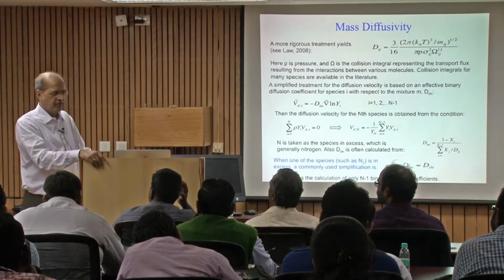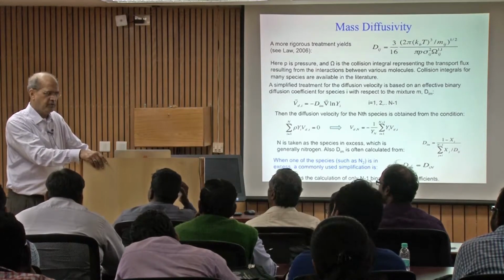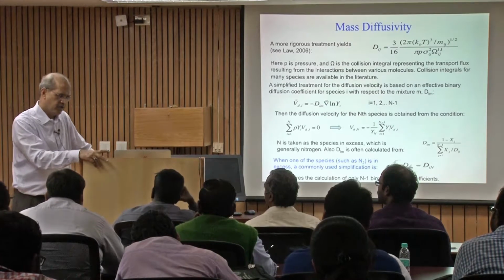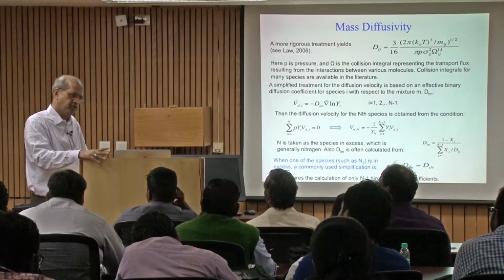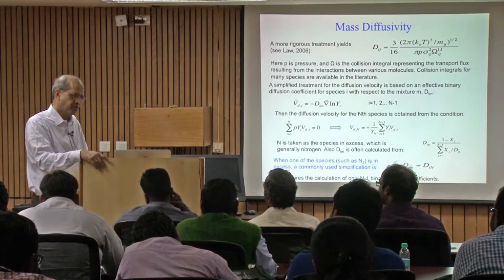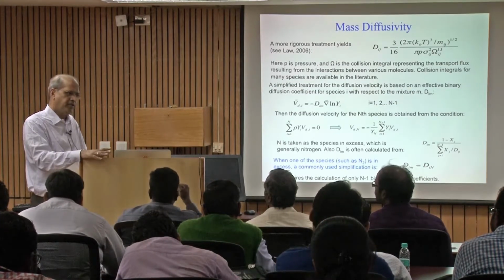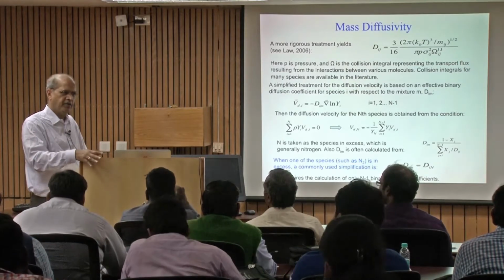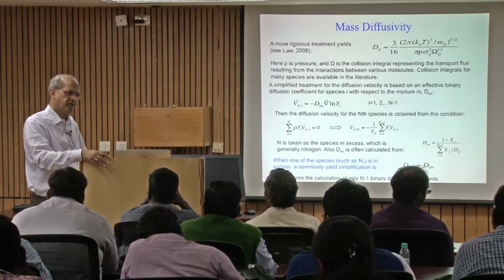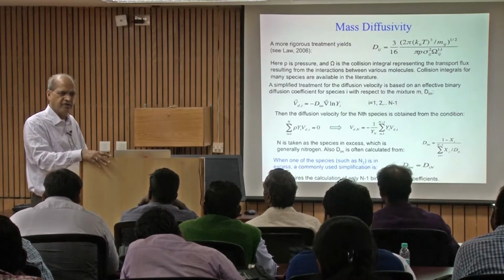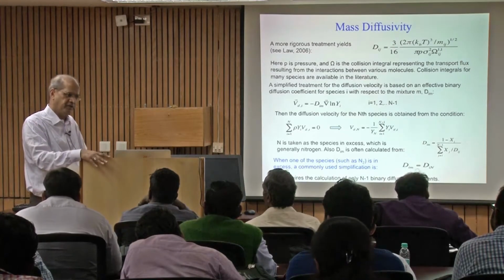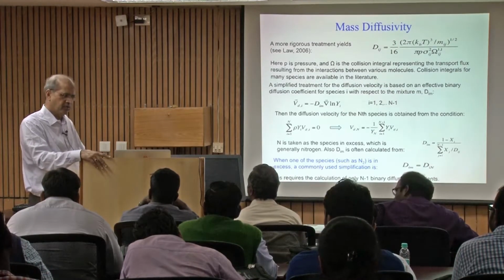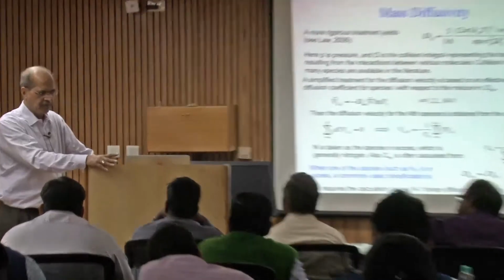Because diffusion flame structure, flame shape mostly is determined by the diffusivity, or diffusion process, convection and diffusion, unless the flame is near extinction. Okay. Any extreme phenomena, extinction, ignition, near extreme conditions, chemical kinetics is always important, especially the detailed kinetics becomes very important. Okay. Like premixed flame.